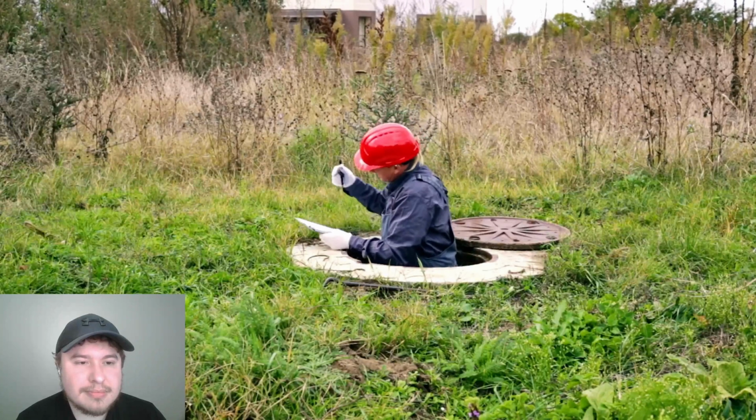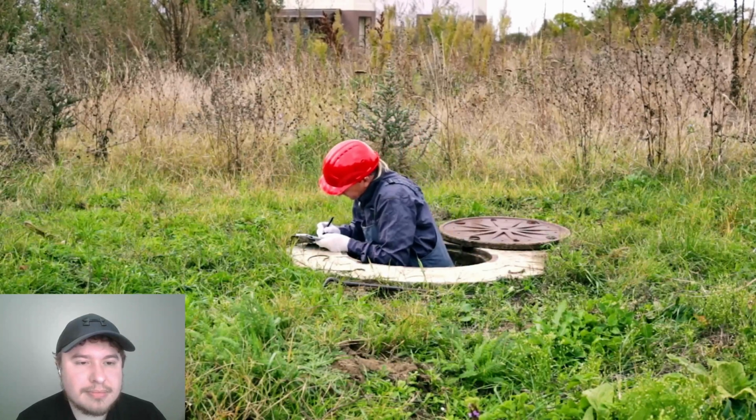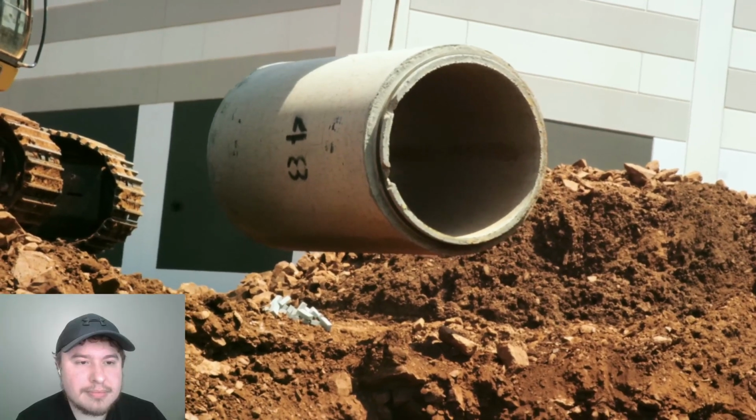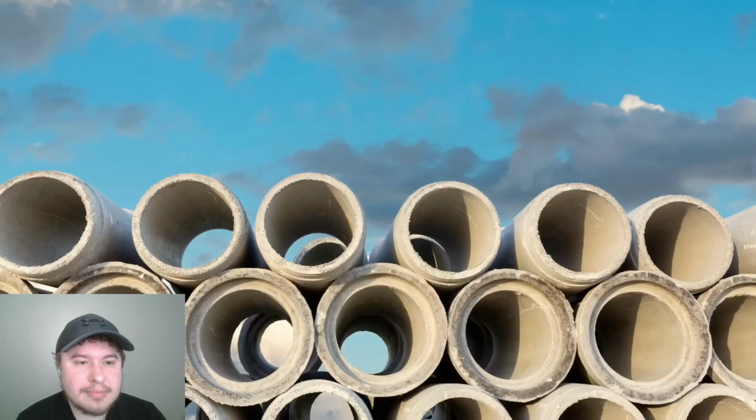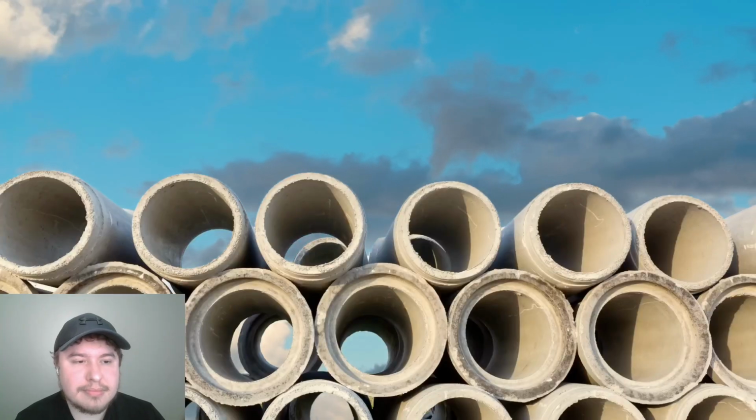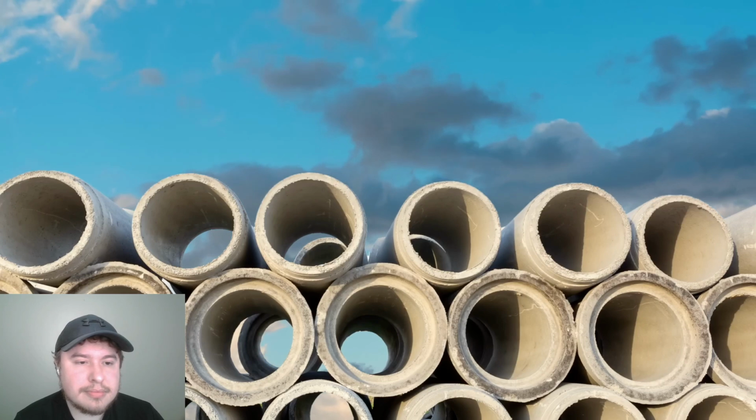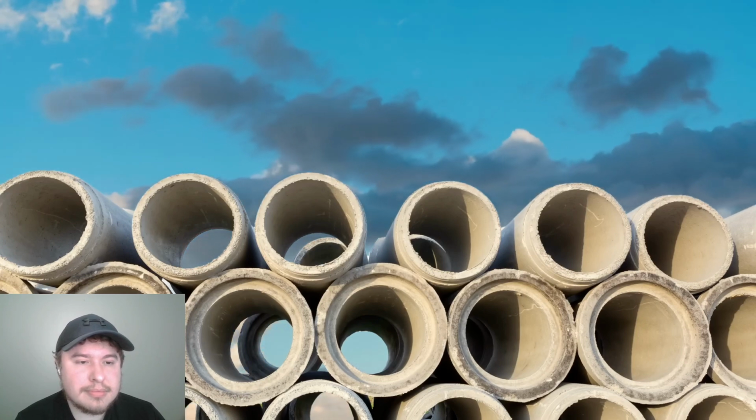It's the best shape for resisting horizontal soil loads. It's easier to manufacture a round shape than a rectangular one. For those reasons, manholes are usually made of pipes. And pipes are round because it's the most efficient hydraulic section. It's one of those questions like the airplane on the treadmill that can spawn unending online debate, but I like pipes, so that's my favorite answer.